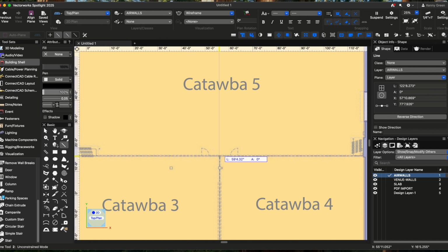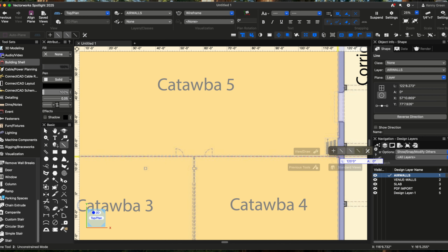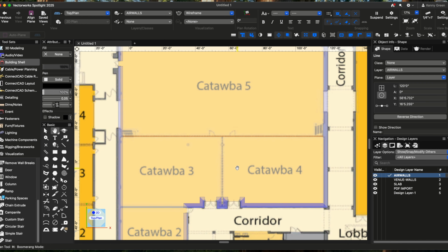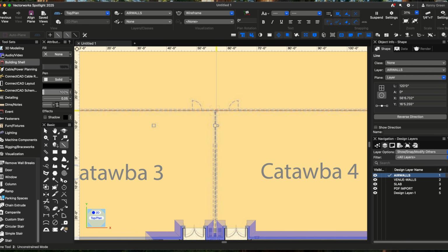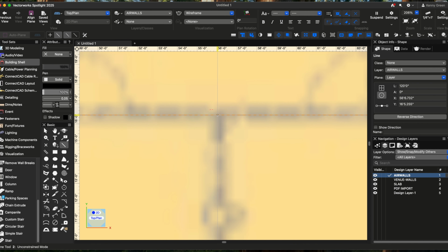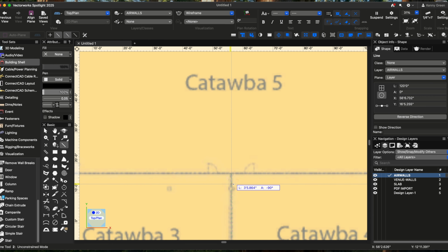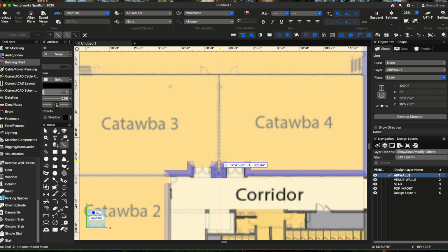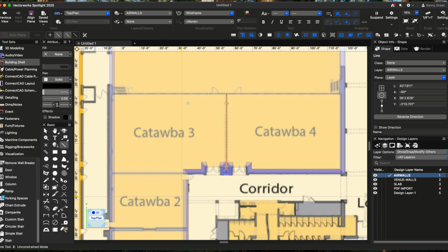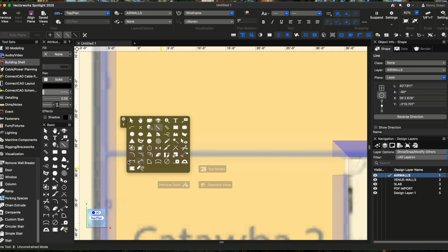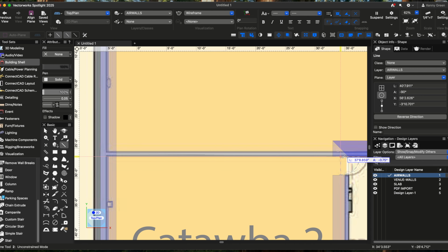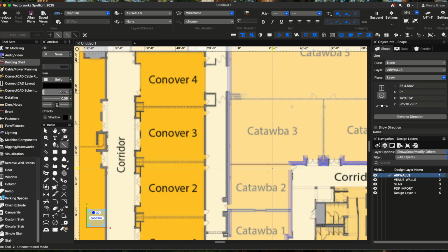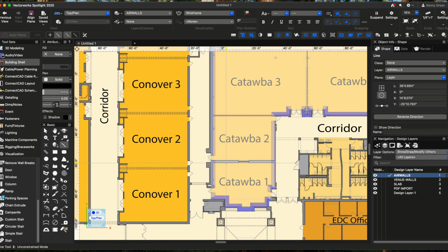And you can see that in this air wall, there's doors. So actually, if you want, you can use the wall tool like we have just done and put doors in. You can do that as well if you need them. If you know that factually that air wall is going to be closed and you do not need it for your event, then you're probably best off to go ahead and use the real wall tool and put the doors in, because that's what reality is going to be for you. But for this exercise right here, we're just drawing in regular lines. Oh, this is actually interior walls right here. So this actually, we need to draw walls right there. But we're not even playing down here in this space.